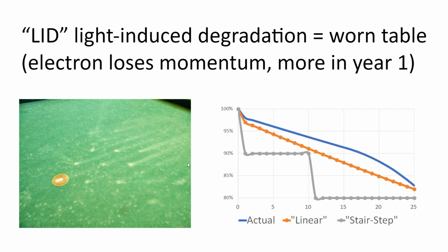here's one that is kind of interesting. This is what's responsible for the sudden degradation of the panel in its first few months of system operation. So there is a burn-in period where the array loses 1 to 3% of its production. It's fascinating to see. I had a project where it was a commercial project built in stages, and we used the same panel and same manufacturer and same inverter for the stages, and you could just see the production difference, this degradation occur.